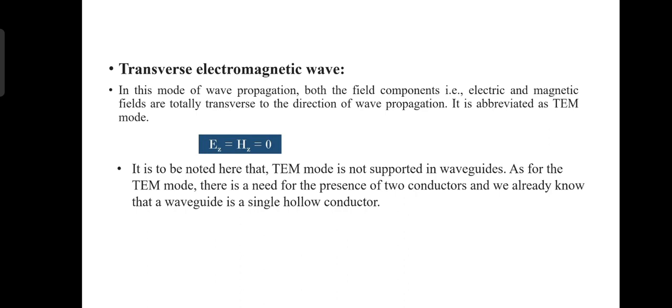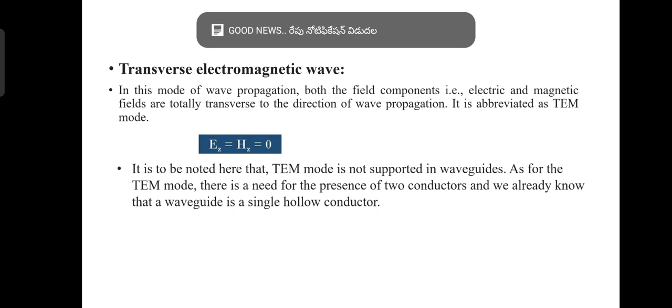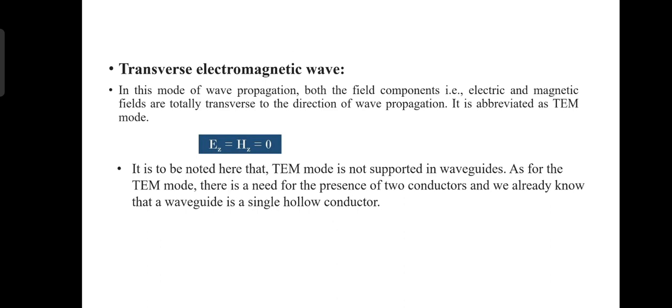It is to be noted here that TEM mode is not supported in waveguides. As for the TEM mode, there is a need for the presence of two conductors, and we already know that a waveguide is a single hollow conductor.